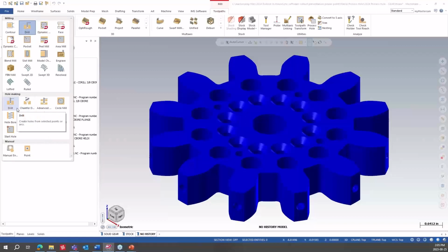It would be, because I don't think it's really looking at the tool itself. It's more looking at the tool path. And as far as I know, like I mentioned earlier, you'd be able to use this on any of the hole making tool paths except for FMB drill, the auto drill, and the start hole. Everything else is available. So I don't think it really looks at the tool itself. You could use any tool you want, I think. So I think that would work as a process. Yeah, and it may depend on how complex the form tools are, but that's something that we can definitely look at offline, James, for you specifically.